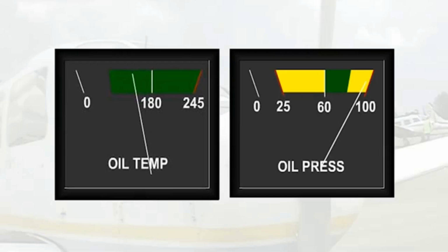If, on the other hand, the high oil pressure is accompanied by a low oil temperature, the high oil pressure may be caused by the relatively high viscosity of the oil at low temperatures, making it difficult for the oil to pass through the engine. The oil pressure relief valve may be unable to control the situation completely until the oil temperature rises. As was stated before, as long as the oil pressure drops to normal as the engine warms up, this situation can be considered acceptable. However, if the pressure remains at dangerously high values, the engine must be stopped to prevent damage.